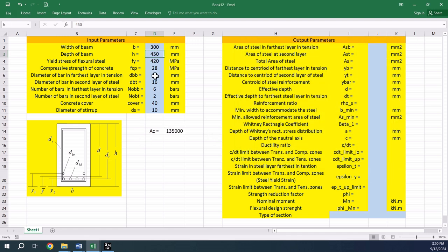If you click here, you will see that this address has been assigned the name H and the value has been calculated without referring here to the specific addresses. So again, we have two methods. You can either directly insert the addresses here and multiply them by each other to have the area of concrete in the cross section, or you can assign names to the addresses that you want, and then you can write the equations just as if you would write them on a piece of paper.